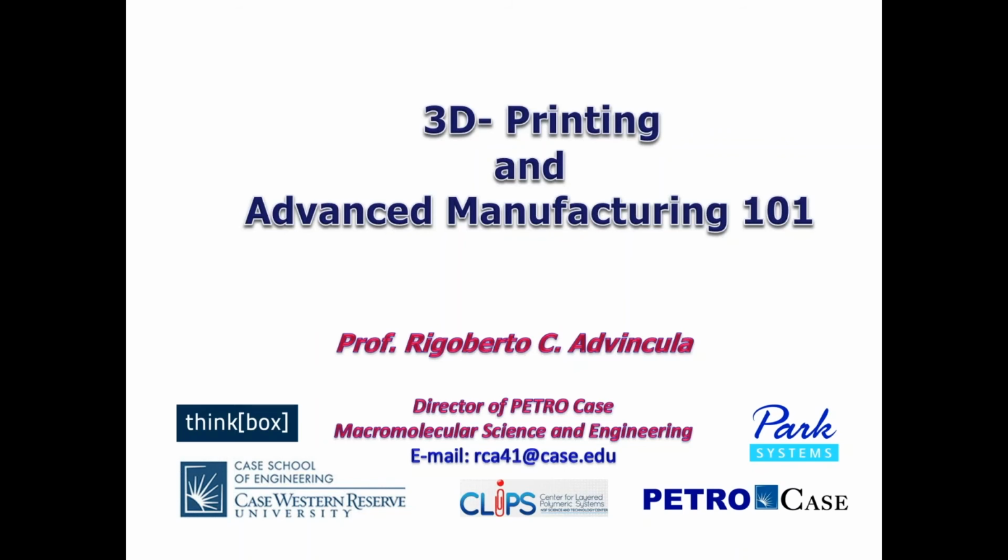Having said those, some of the challenges that I see going forward is addressing the materials needs. It simply is a fact that a 3D printed object is not the same as a traditionally casted, molded, fabricated object because of the failure modes that are introduced during the printing itself. That is, instead of a monolith fabrication, 3D printed materials are produced by lines or additively by layers. And each time you layer a production, you are producing failure or quenching points. So materials is a big challenge, or having the right combination of materials and processing is a big challenge that needs to be overcome in order to be an actual replacement industry.